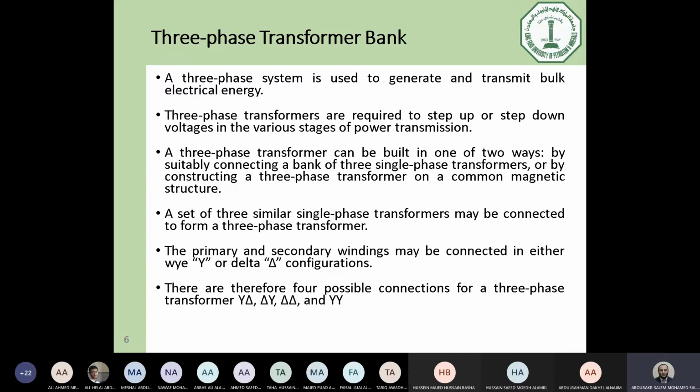So we have to use a step-up transformer at the beginning of transmission, say stepping up from 20 kilovolt to 500 kilovolt. And after transmitting this power, at the receiving end, we should step down the voltage again. However, we step down the voltage in many steps, not in one step like in the beginning, like the stepping up, because we need to distribute this power among industrial loads and domestic loads.